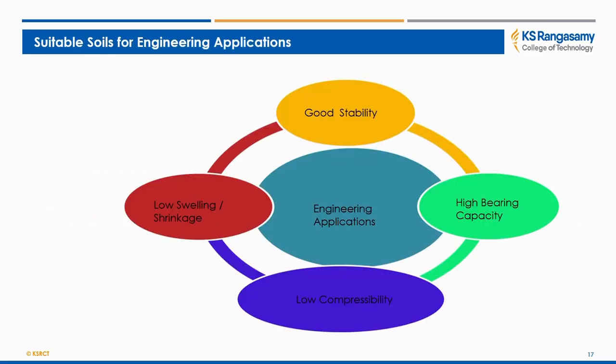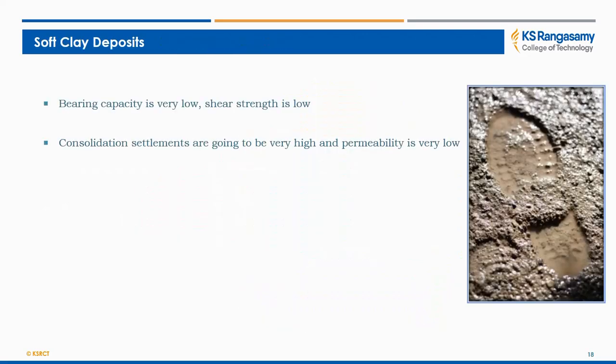The suitable soils for engineering applications should have good stability, high bearing capacity, low compressibility, and low swelling or shrinkage. In soft clay deposits the bearing capacity is very low and the shear strength is also very low. Consolidation settlements are very high and permeability is very low.